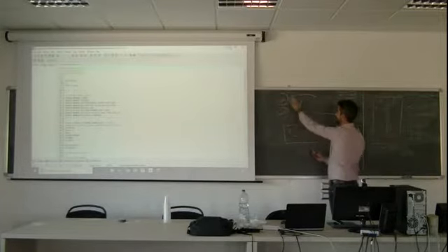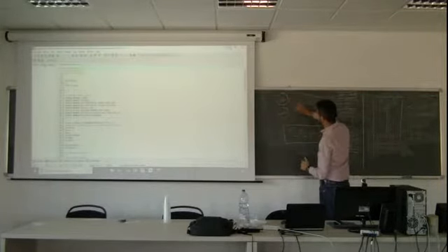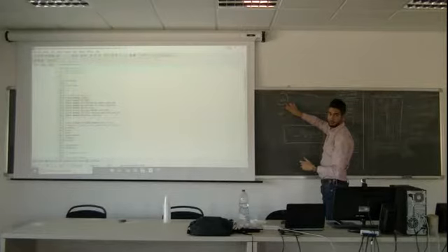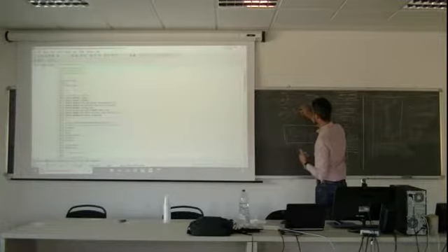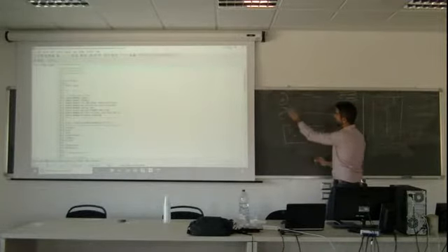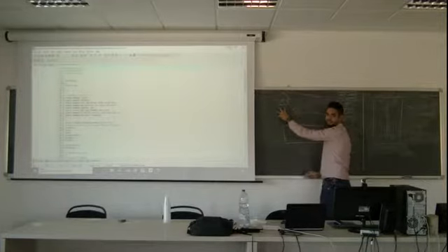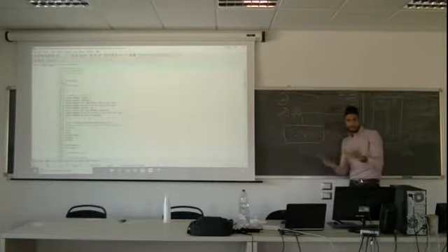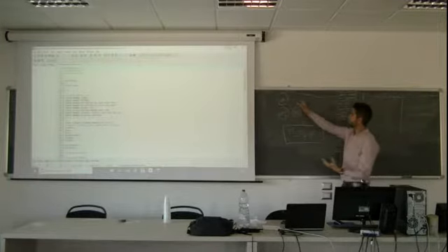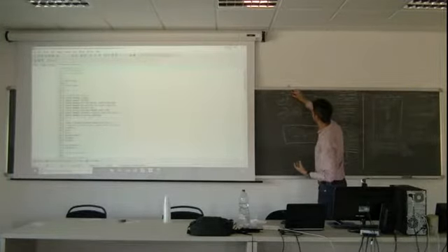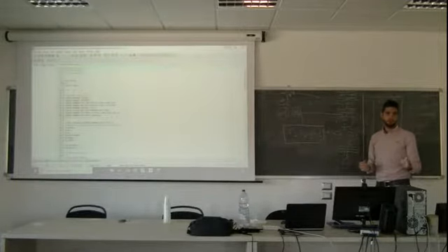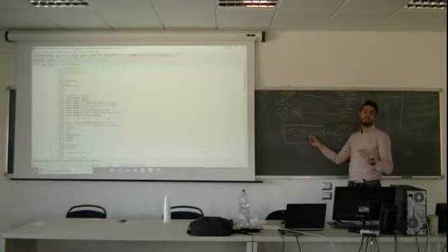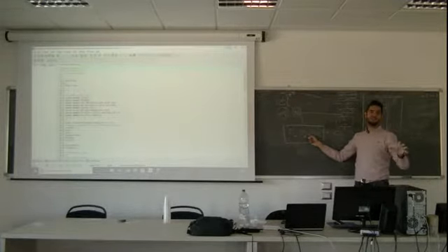Yesterday, the new assumption for the second iteration was directly the solution. Right? Now, what I propose is for the new assumption, assumption number 2, it will be a mixture between this solution and this assumption. It will be a weighted. Usually 80% this value and 20% this value. That means the relaxing factor is 0.8. Usually for energy equations, relaxing factor is 0.9, 0.8. Usually.